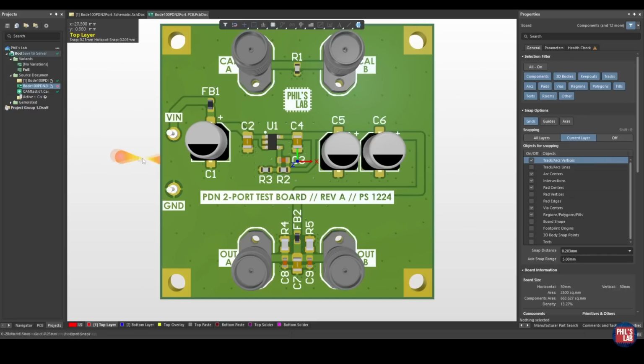We have an input part where we can feed in from, for instance, a lab power supply. We can have some series filtering, bulk decoupling before we feed into a low dropout linear regulator with its input and output caps and feedback network. We feed with known trace dimensions, that is lengths, widths, and distance from reference planes and so on, through some bulk decoupling caps. We follow a longer trace into a filtering element and then into some decoupling capacitors as well as some load resistors. And that point right at the bottom here is our point of load, which should simulate or emulate an integrated circuit pin, which has some larger and some smaller capacitors and has a load as well. But for the sake of this board, it provides some easy measurement points for our 2-port shunt-through measurement method. And we'll go into more detail later on.